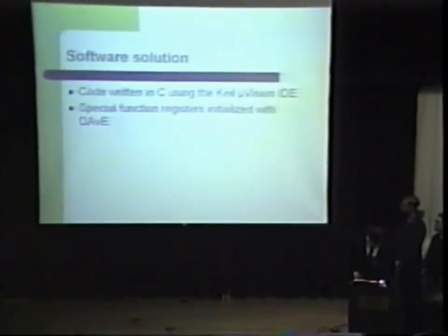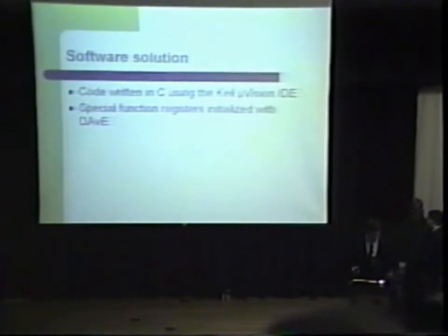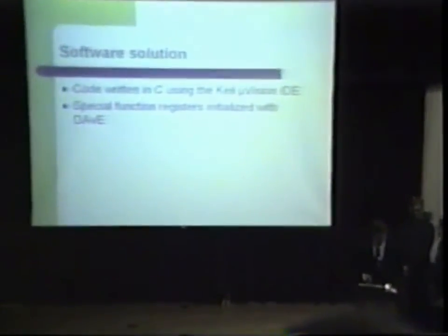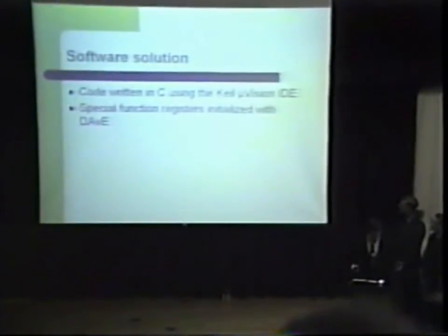The software solution for our project: the code was written in C using the Keil MicroVision IDE. What an IDE does is it lets you write code in C, and then it takes that code and converts it to assembly, and then takes that assembly code and generates a hex file, which will run off your processor.